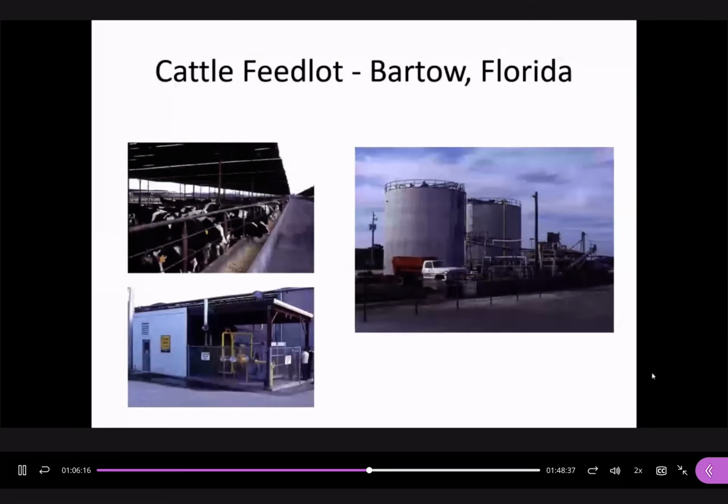Cattle feedlot. Right. So you can see here, anaerobic treatment is used in different scenarios compared to aerobic treatment, right? What is the feature of the sludge? What is XW? What's the typical range? Concentration over 10,000 milligram per liter. So it's a very high concentration. Here we are talking about some agricultural wastewater, some industrial wastewater, with high organic concentration. The COD concentration could be thousands or even more than 10,000. Municipal wastewater is 500, right? So it's a different scale.